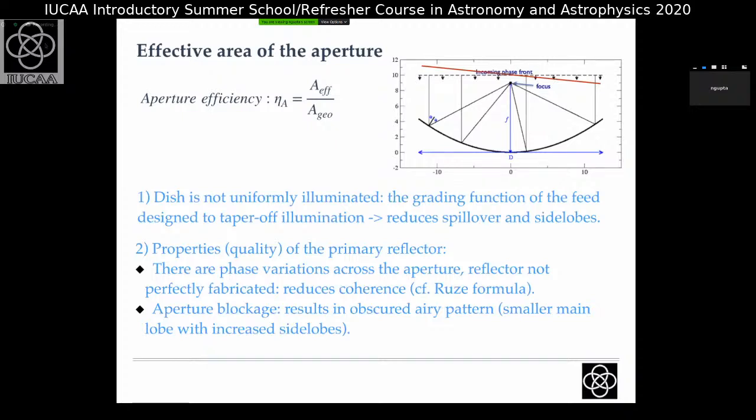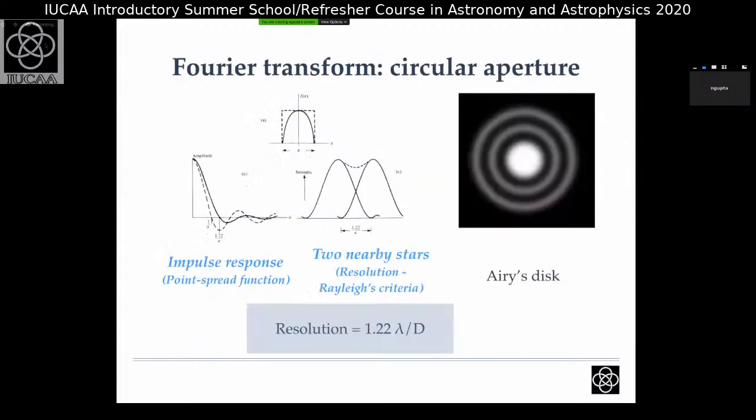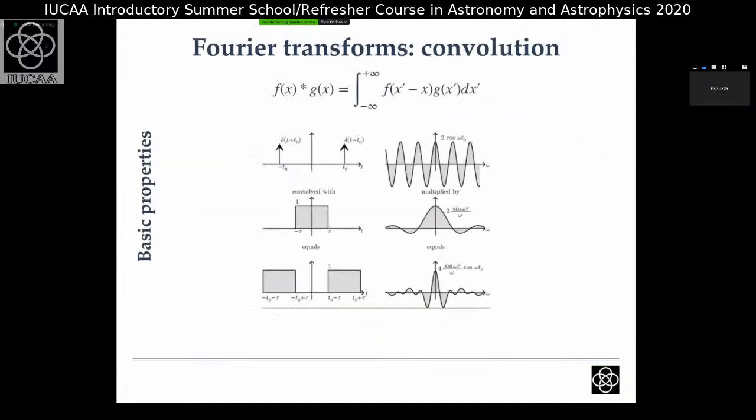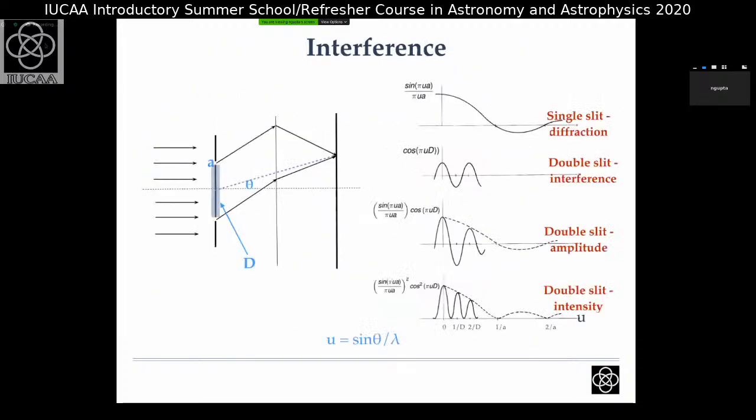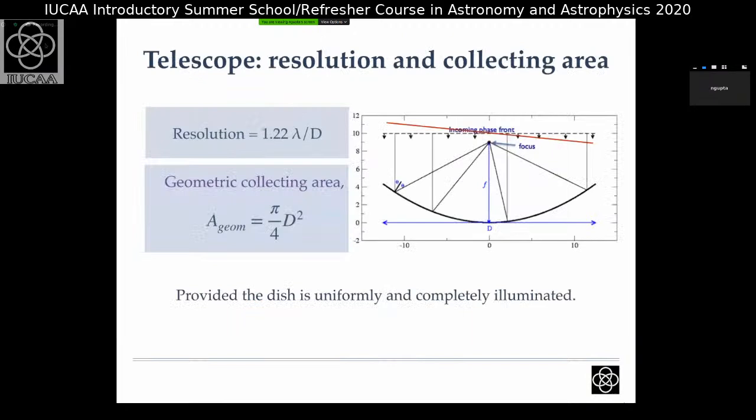And the second thing, if you go back to my Fourier transforms, is that wherever I come across sharp edges, I end up with a function which has ringing, right? If I take something like a nice Gaussian, it falls off nicely in the other domain also. But whenever I have sharp edges, like a box function especially, I end up with a corresponding Fourier transform which has these side lobes and ringing. That is something which I do not want my instrument to have.